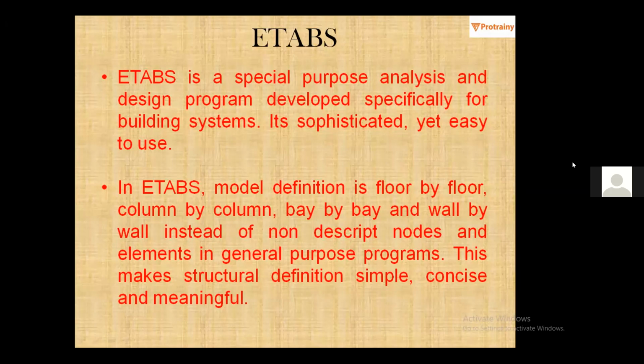Now, the thing is that in this course, we are going to teach you ETABS as well as STAAD. So you don't have to compare it. But this is how ETABS works. ETABS doesn't work on nodes and the connection between these nodes. It works, as I told you, the model is defined on a floor by floor, column by column, and bay by bay basis. This makes structural definition simple, concise, and meaningful.